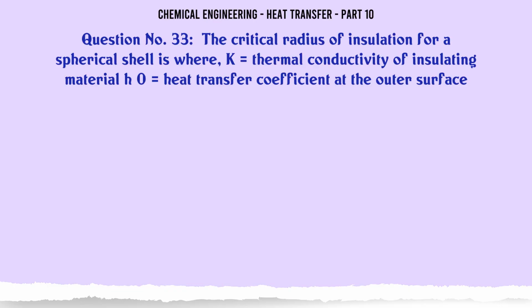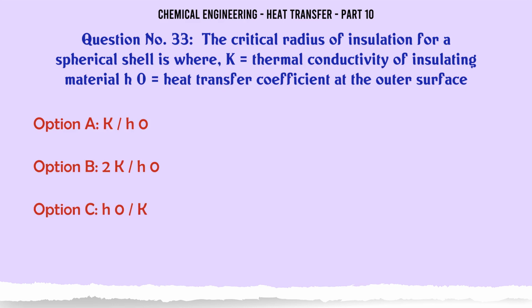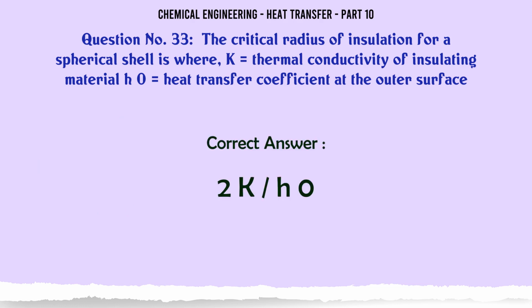The critical radius of insulation for a spherical shell is, where K is the thermal conductivity of the insulating material and H0 is the heat transfer coefficient at the outer surface: A. KH0, B. 2KH0, C. H0K, D. H02K. The correct answer is 2KH0.